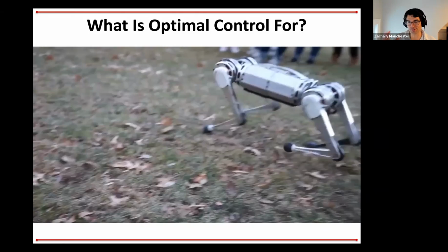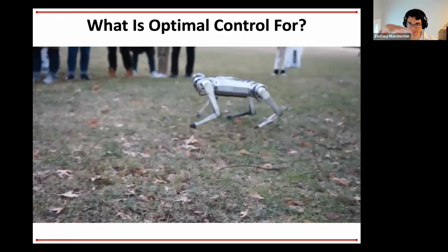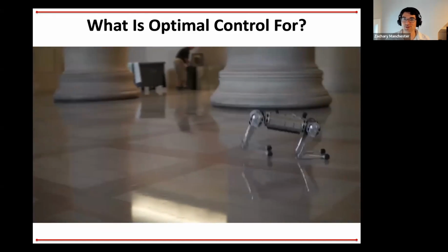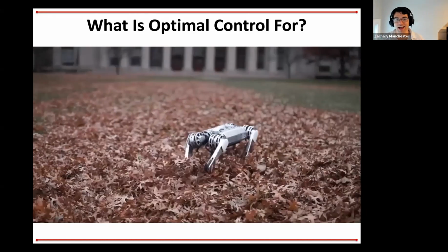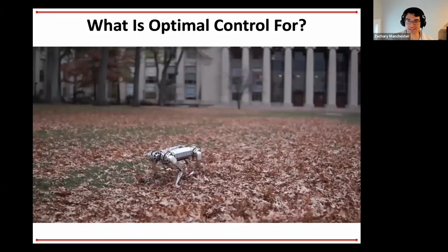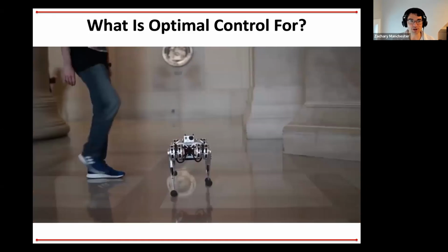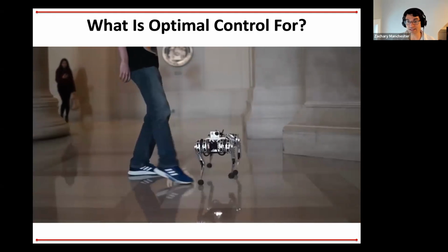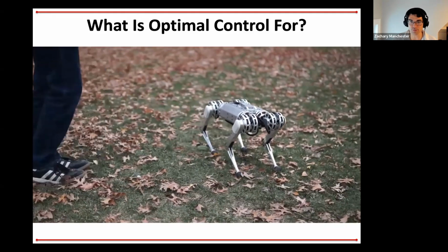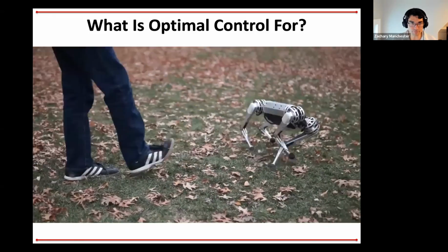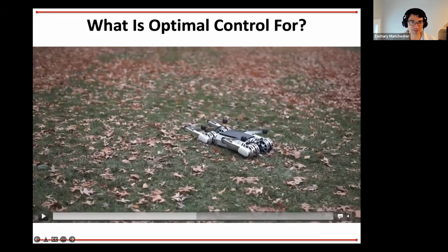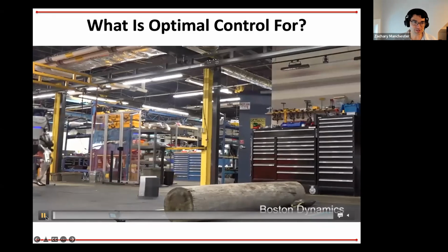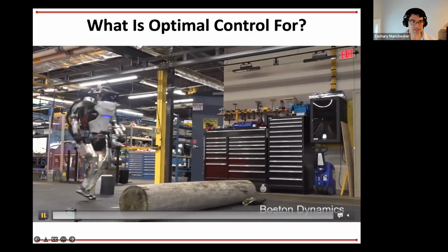So there's a linear MPC layer at the top, and then there's a bunch of clever low-level control stuff going on so that you can treat this thing at the high level as a linear system, which it is most definitely not, right? It's super nonlinear. So there's a bunch of secret sauce in there, but at the highest level, it is again a linear model predictive control problem or convex model predictive control problem that gets solved. And maybe most exciting and state of the art of all the stuff is everyone's seen this stuff, Boston Dynamics.